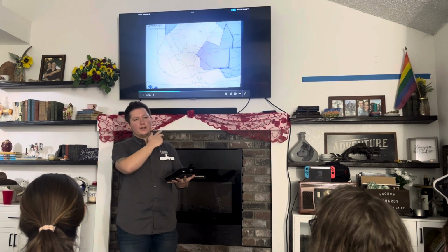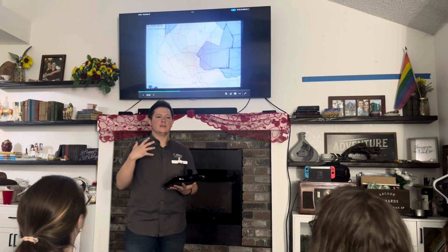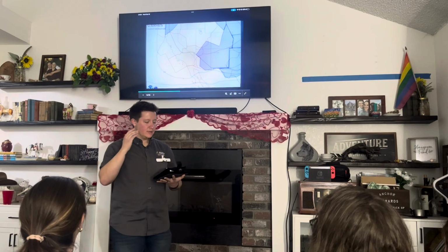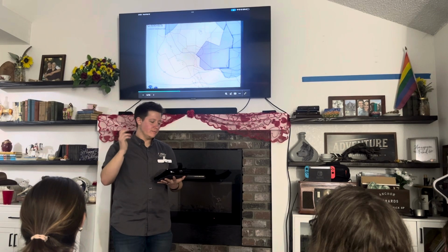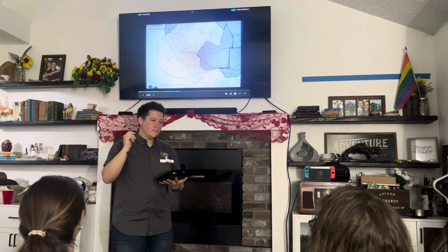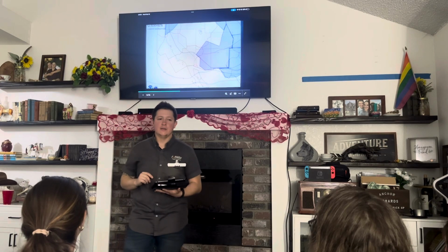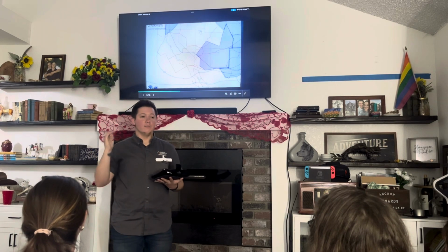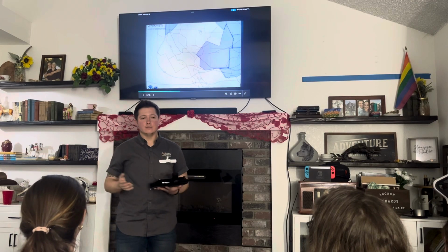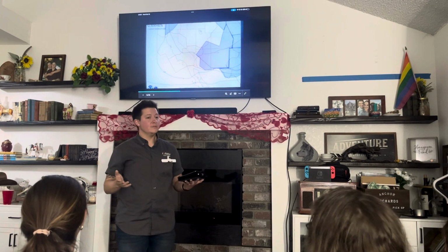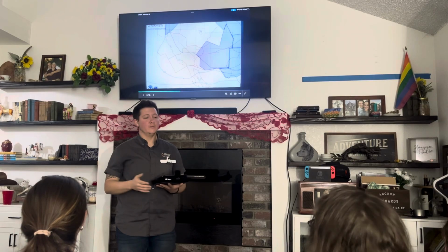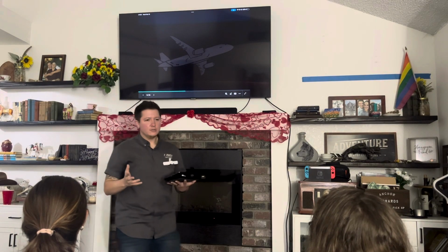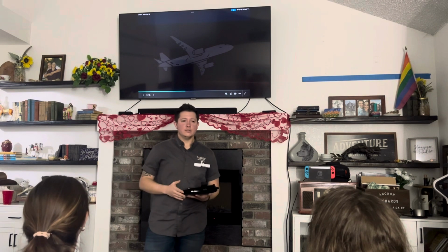So this one spanning out to the Pacific Ocean says that the freezing level starts at 8,000 feet. And then we also have this one that's kind of in between where California meets Nevada is going to be somewhere around 4,000 feet actually. So anywhere from 4,000 to 8,000 and above that will be above the freezing level, which we are. Remember, we're going at 11,000, so we can anticipate we're going to be in that freezing level. So seeing that we have these two conditions, we know that icing is going to be present.